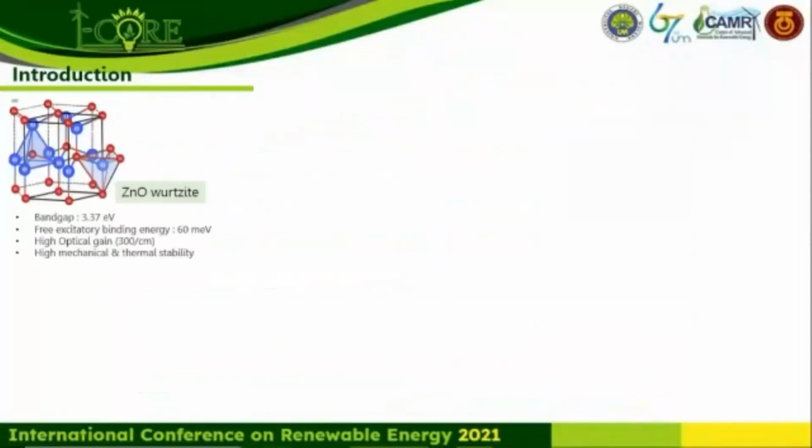First of all, zinc oxide is classified as a semiconductor which possesses a wide bandgap of around 3.37 electron volts, and also has free exciton binding energy, great optical gain, and exceptional mechanical and high thermal stability. Zinc oxide is specifically attractive for a wide range of functions such as conductive oxide, anti-static coatings, touchscreen sensors and panels, and wide bandgap electronic devices.